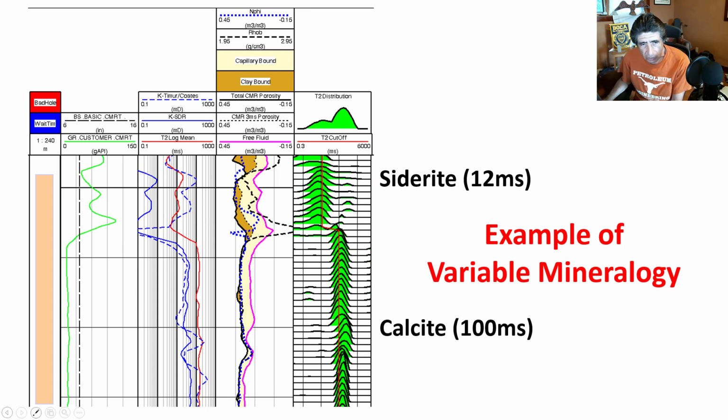case of calcite, the second part of the rock, we have paramagnetic materials, but not in the same quantity and quality. So what happens is that even though you may have the same pore sizes, when you have the pores lined with more paramagnetic materials, then the surface effects will be accelerated. And that's what this plot shows, that sometimes we have to also take into account the mineralogy of the rocks, because variations of minerals, especially paramagnetic materials, will also cause shifts in the dominant peak, not due to the size of the pores, but due to the variations of the minerals that are lying in the pores.